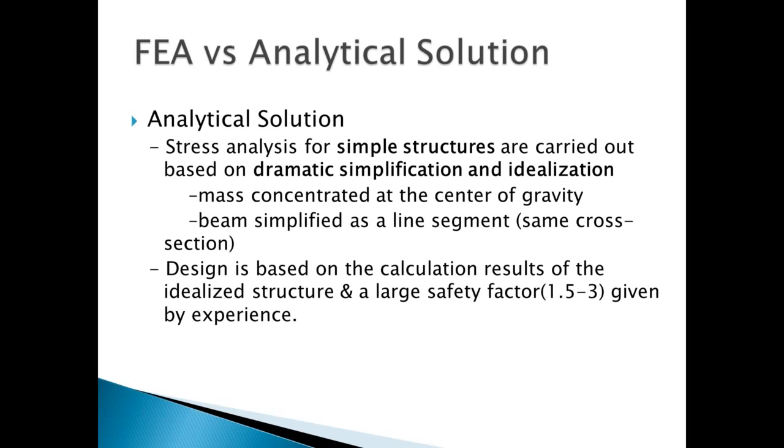calculations. So first, let's take a look at the analytical solution, which I'm sure you're all very familiar with. It's typically used for simple structures, and it's based on dramatic simplifications and idealizations. Therefore, it's ideally used, once again, for simple projects, and it's very limited when it comes to complex or more finer analysis types. And the design is based on calculation results of idealized structures and large safety factors. So overall, with the analytical solution, although it's very easy and very simple, it does tend to give overly conservative calculations, especially for higher end projects.